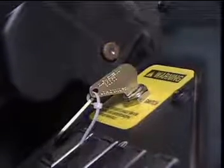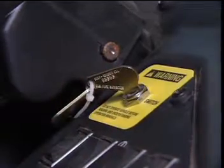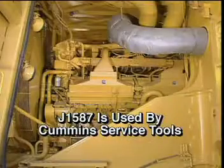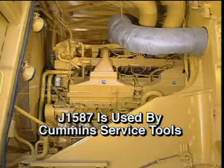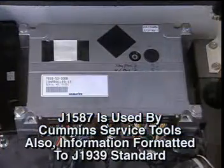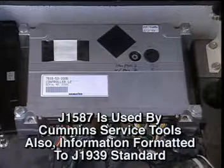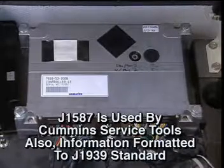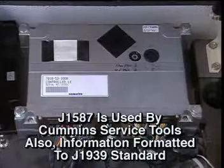The data link is activated whenever the key switch is in the on position, regardless of whether or not the engine is running. With the current QSK 45 and 60 engines, the J1587 data link is used by Cummins service tools. In addition, the data link provides information, formatted according to the SAE J1939 standard, to additional data logging equipment, such as electronic dashboards or other equipment's ECMs.